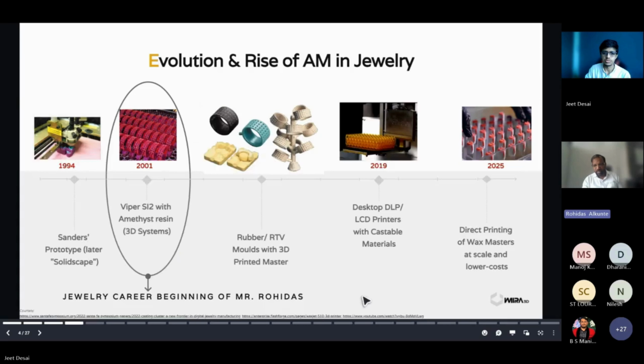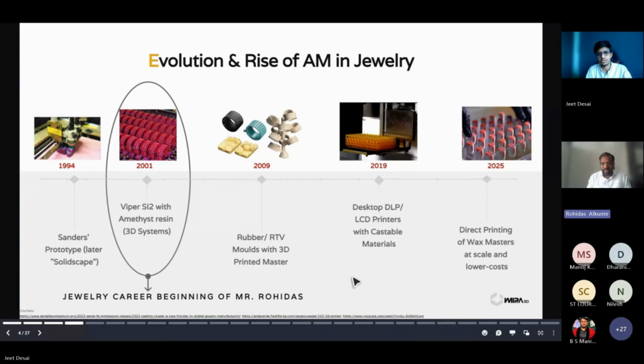This silver casting is finished and kept as a master model. So whenever you get an order, they inject the wax piece through the rubber mold and produce multiple pieces. The requirement is to produce similar multiple pieces, maybe 1,000 or 500, depending on the orders, with the same mold. So this is how they used to do patterning.